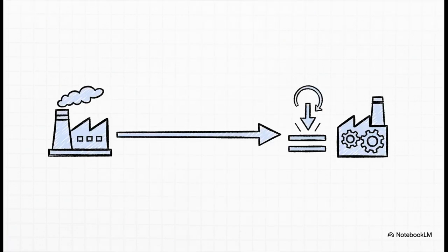The solution is called power factor correction. What you do is add a new component, a capacitor, right next to the motor. You can think of it like giving the motor its own little local reservoir for that sloshing reactive power. Now, the capacitor and the motor can just trade that energy back and forth between themselves, so the power grid doesn't have to waste effort sending it all the way down the line.